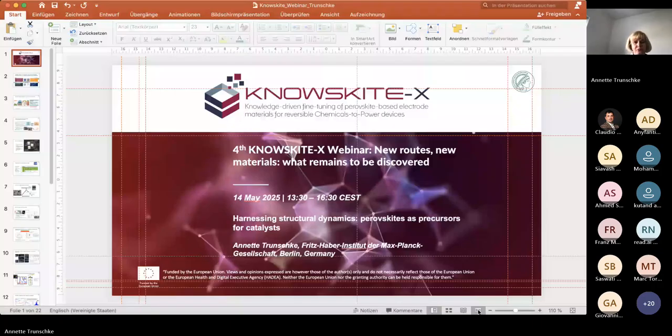And by varying these parameters, you can control the phase composition of your product, and you can also control the particle size. And therefore, we optimize the synthesis for each perovskite, and in this way, we came to very reproducible synthesis of very small size primary particles in which the elements are very homogeneously distributed, like in this lanthanum cobalt oxide.